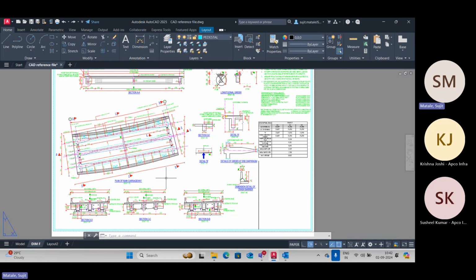Once you are done with that, then comes the next step that you have Excel and TED, and you combine them and get automated stuff going on. Then comes a level where you open Revit, develop your models in Revit and use Sofistik for your further analysis. Then further comes a step where you use Rhino and Grasshopper as a pre-processing unit and develop your models. So there are steps to it. But if you do this, this is more than sufficient for any bridge engineer in practice. One really need not look at the rest of the ways further.